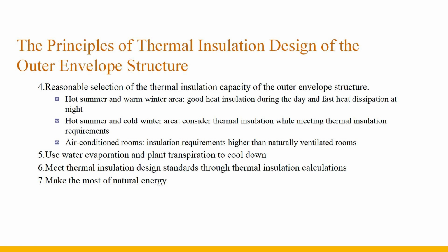Are there any downsides? Due to the need to consider frost protection, this method is only suitable for warm areas. Due to the need to consider the weight of water, soil, and plants, this method increases the structural load and puts forward high requirements for root blocking, waterproofing, and insect control. Although the water storage roof has a good heat insulation effect during the day, it is difficult to use the roof to dissipate heat at night due to its strong heat storage capacity.